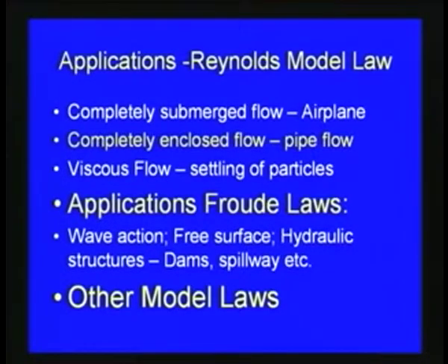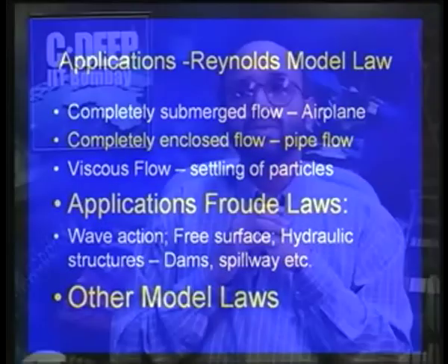Similarly, as I mentioned, where Froude law or Froude number is considered, wherever the gravitational effect is more important, Froude law is used. So, cases like wave action, like estuary models or like Portland Harbor models, in these models we can use the Froude law.